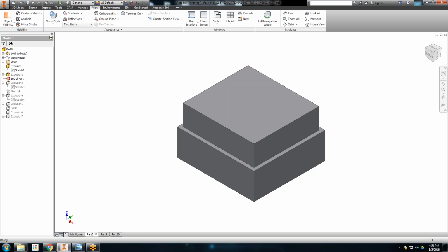So what I have the kids do is there's a safety boundary. This allows me to not be accurate when I'm making the raw stock, and allows me to not be accurate when I'm trying to find that corner in the mill. I can just throw a stock piece in there, and regardless of how accurate I put it in there, I've got enough extra material around the outside that it's going to make my part just fine.